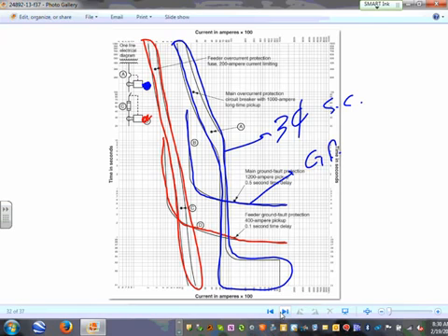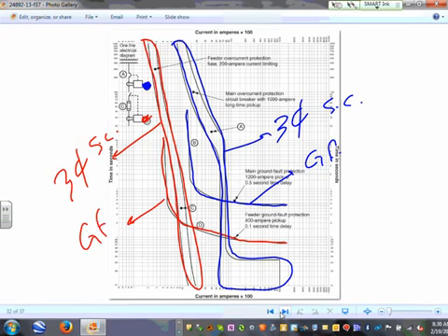The same thing for the fuse here, guys. The fuse, the big guy is, what did we say, three-phase, short circuit, and the little guy is the ground fault for it. So when you have the same thing in the same device, okay? So when you have a ground fault, what I'm trying to get to, you coordinate ground fault with ground fault, three-phase with three-phase. You don't have to coordinate a three-phase and a ground fault. You have to look at it, but typically ground fault with a ground fault, three-phase with three-phase, inside the same device.